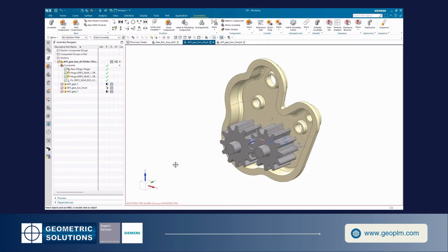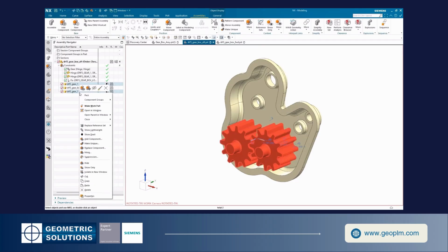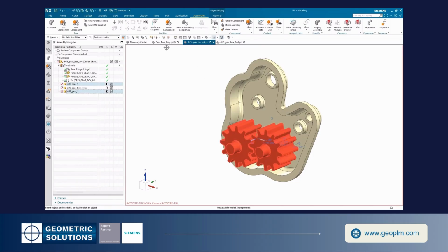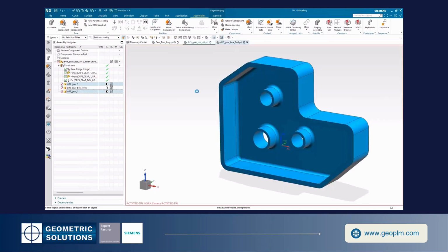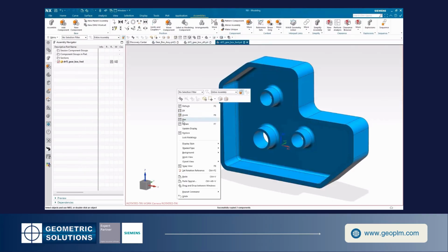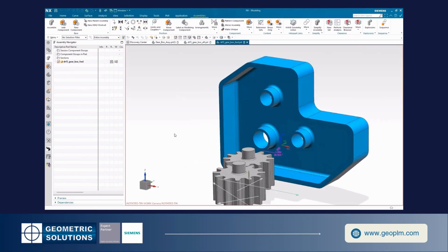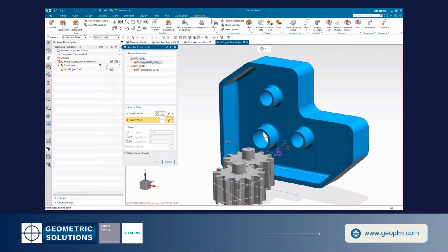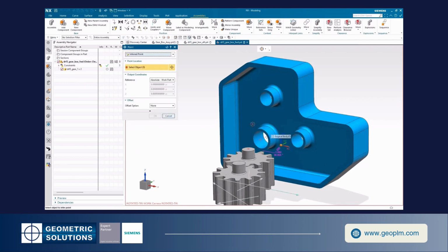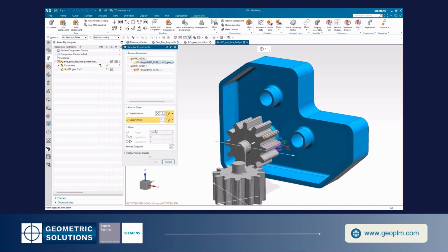Finally, I'm going to show a mixed case where we have external joints plus an internal coupler. I'm going to add these gears to another part with a different gearbox. As we can see in this model, currently there are no constraints here, so the hinge joints have become external now, and we get the opportunity to resolve them with the constraint dialog. The gear coupler remains internal to these two gears, so it will be copied automatically with the components and update correctly when the hinge joints are resolved.